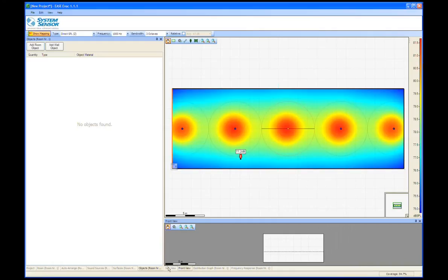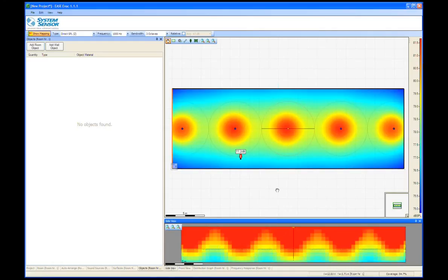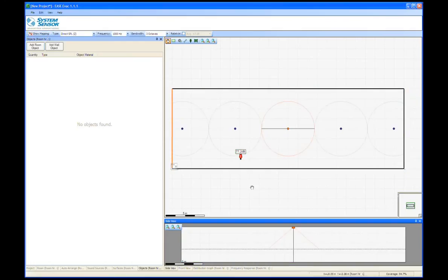If we have a loudspeaker selected, we can see a side view of the loudspeaker and the SPL map that's showing there. If I turn off the map, you can see the coverage cone from the loudspeaker, where it intersects the ear height, and this circle defines the intersection of that coverage cone of the loudspeaker at the ear height.